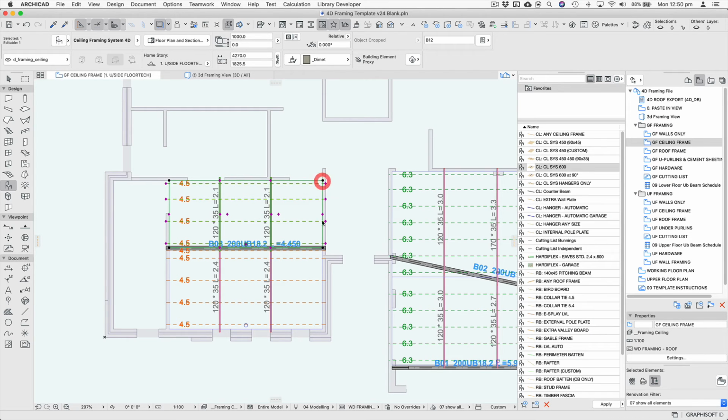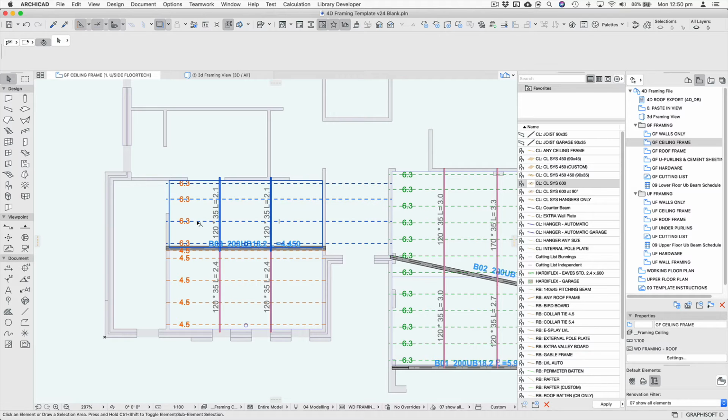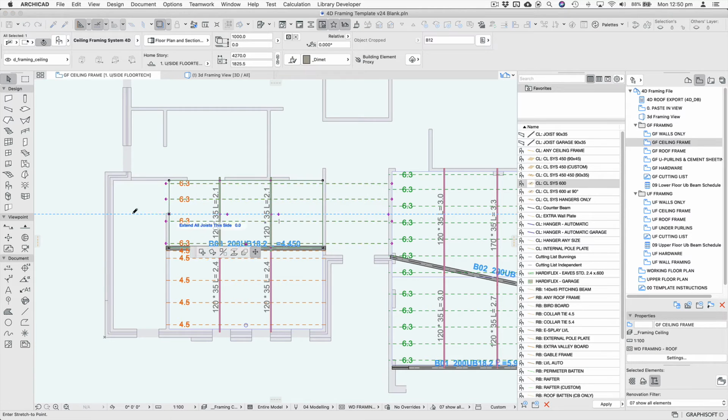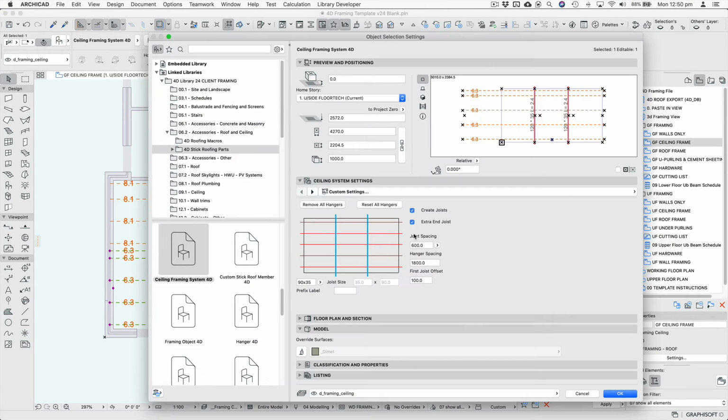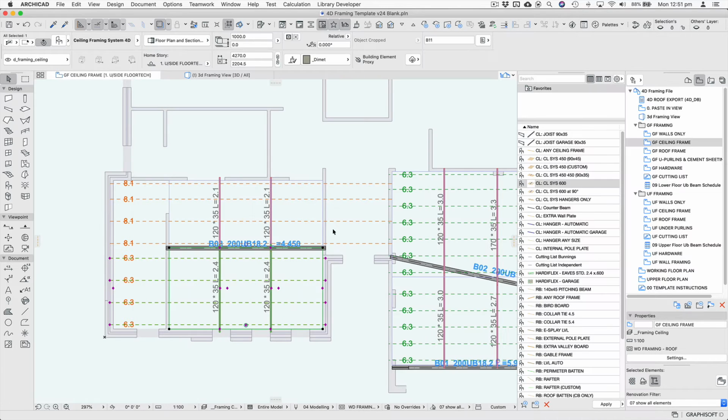up to the beam. Now here I might extend these joists through. That's 1840. So let's have a look. Let's measure that span. 1750, that should be okay. And here, see there's a hot spot in the middle here that extends every joist on that side, not just individual joists. So if I open that up, I'll turn off that extra joist.